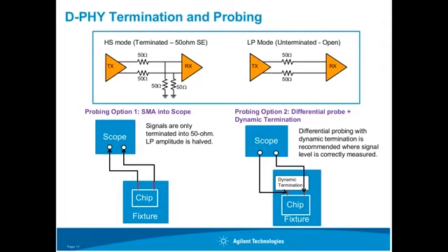Just to start with, there are two limitations using the scope protocol decoder. The scope protocol decoder is a very good way to debug and correlate physical and protocol layer issues, but there are definitely some limitations there as well. The two things are the memory and the hardware trigger that the protocol analyzer offers.